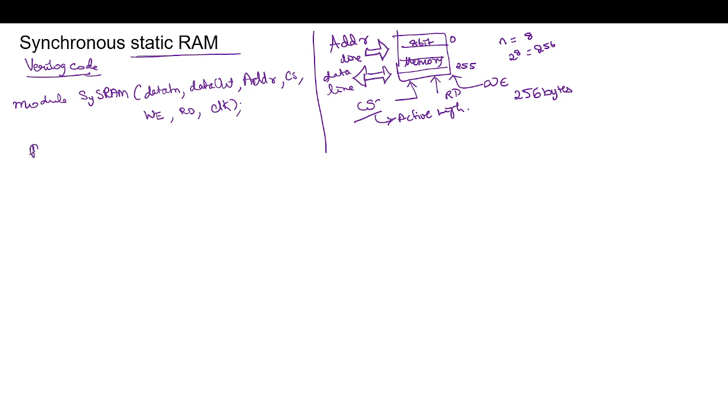So now we need to define the bits. Let us define using the parameter. So my address is 8. If I define it as parameter, next time in the code I can directly use ADR to refer to 8. So if I want to change it to 16 bit, here I can directly change it to 16. That is the advantage of using this parameter.